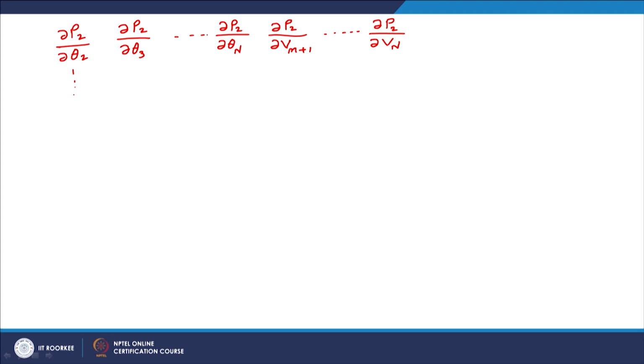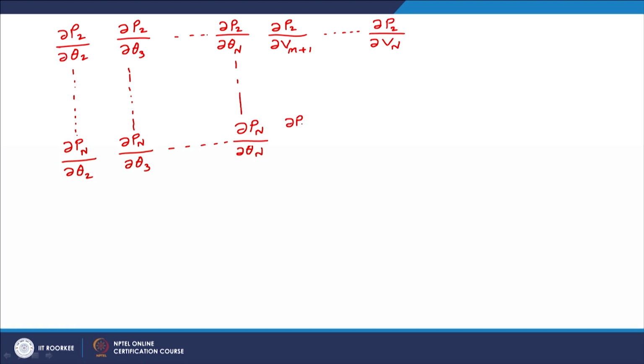Then we collect all these P's and we get del Pn by del theta 2, del Pn by del theta 3, dot dot dot, del Pn by del theta n, then del Pn by del V m plus 1, dot dot dot, del Pn by del Vn. Then start the Q.